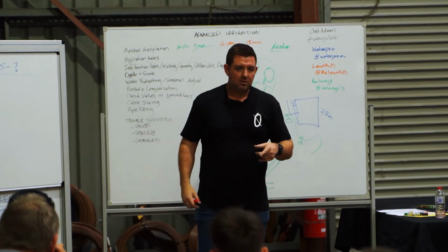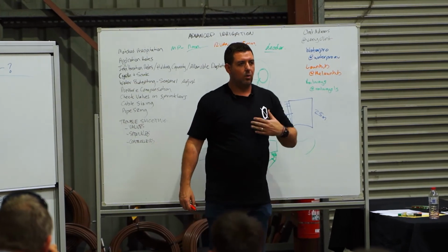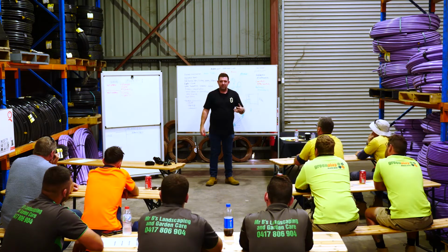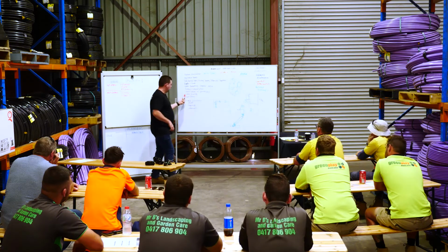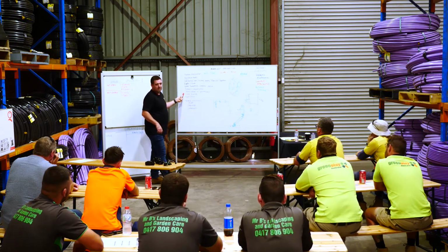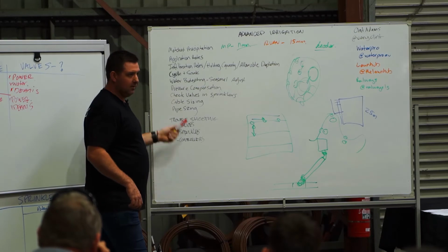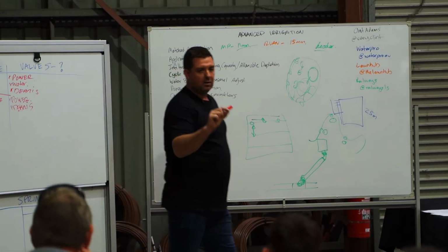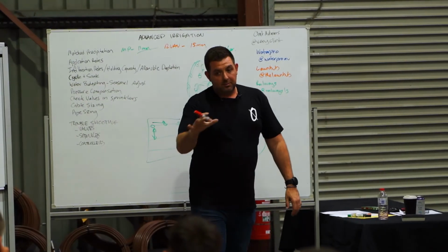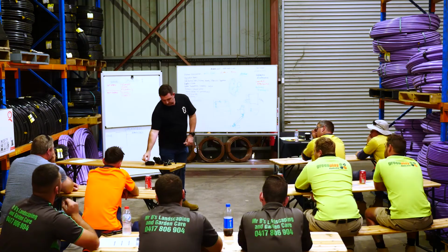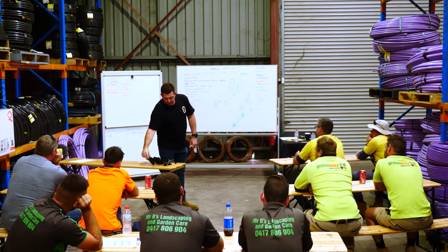When that happens, you find that it's not a case that the water's coming out at the same flow. It might just be that the last sprinkler is just leaking. Obviously, it's going to leak for 10 minutes or 4 minutes from a check valve. It's going to keep leaking forever if there's a rock in the valve. Same situation, you'll take it apart and check that there's no rock in there.